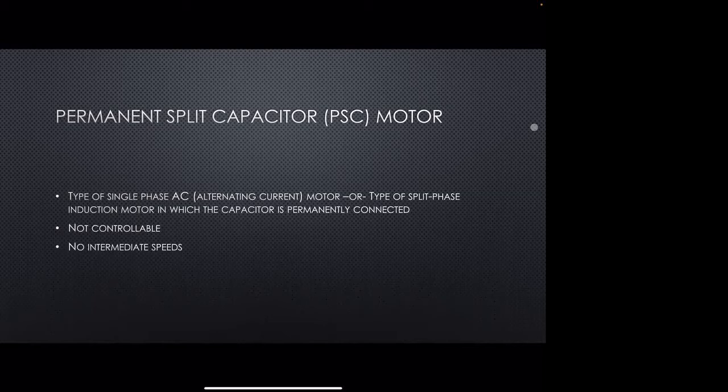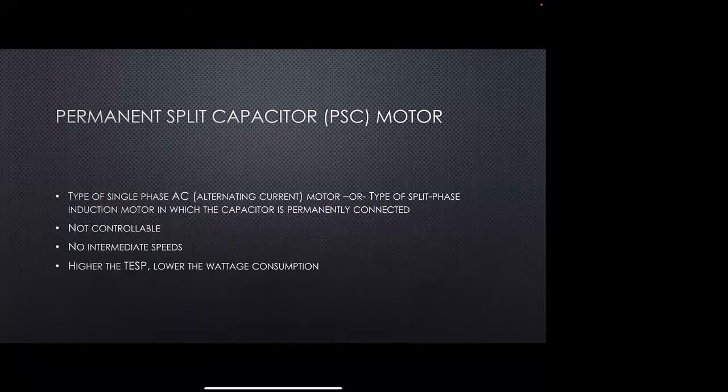We do have speed taps that we get to select, though, and we have to understand how we're selecting and what we're selecting those to. And with the higher total external static pressure of a PSC motor, the wattage consumption is actually lower. That means the energy consumption is going to be lower.